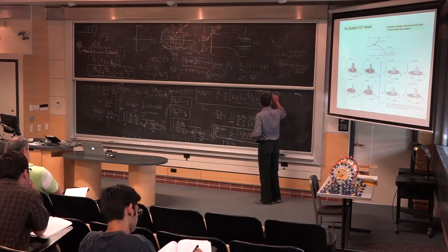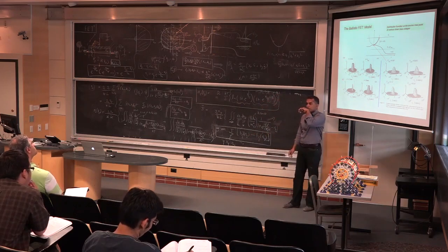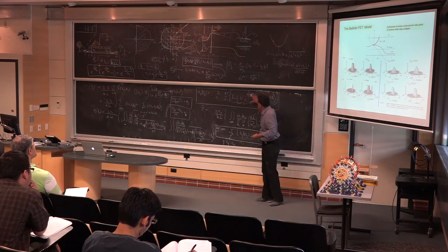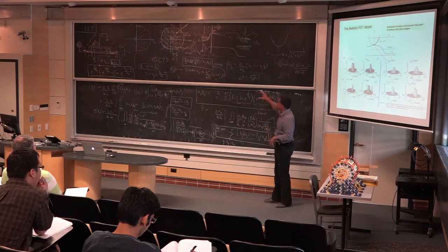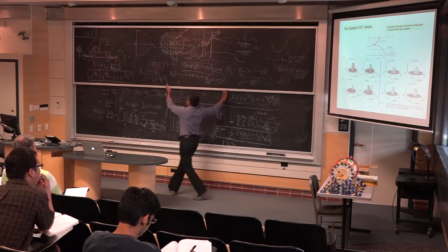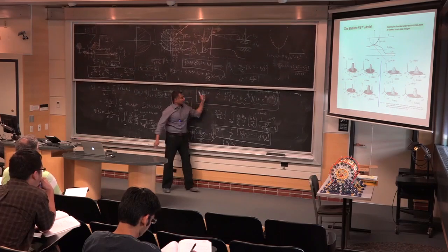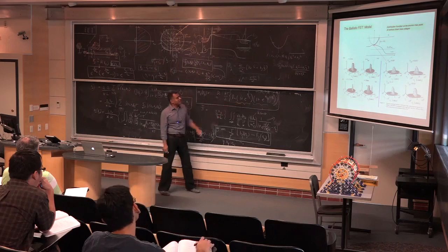Right? This equation is still true. Now, it just happens if VD is 0, then you have equal terms and you have equal half circles. But when VD is not 0, you get this situation. But the carrier density is still controlled by the gate and it has not changed. Does that make sense? I mean, it has remained the same.